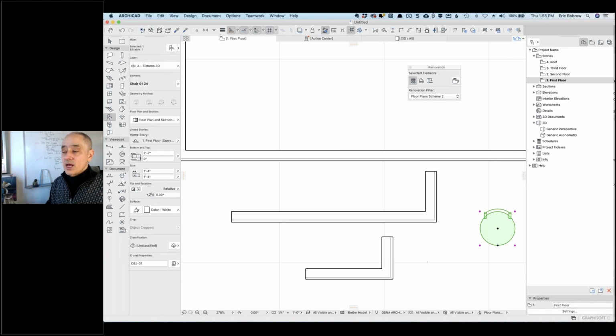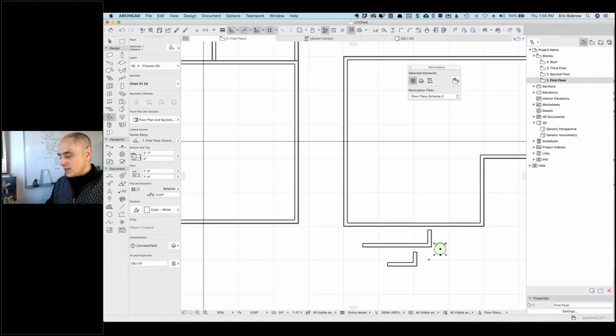You can move that around. I'm sure there have been times you've put in some annotations, some text, and it's just been a little bit too close to something else, and you just want to nudge it, or maybe it's some furniture, etc. Hold down the Shift key and use your keyboard up, right, up, down, right, left to nudge things around. Now I made it 4 inches, so it might not give me as much flexibility, but you can change that at any point, as you saw.